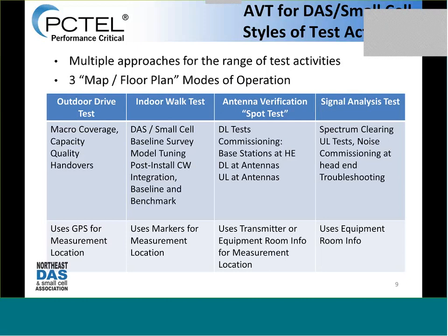A fourth type of testing that's often done, particularly with DASs, is using spectrum analyzers or signal analyzers. If you're doing spectrum clearing at the beginning, just to make sure you know where all the free signals are, a spec an is perfect for that. Oftentimes these uplink tests that we referred to once you've installed the DAS, they're looking for noise levels, the noise floor, additive noise, those types of things that are really done well with the signal analyzer.